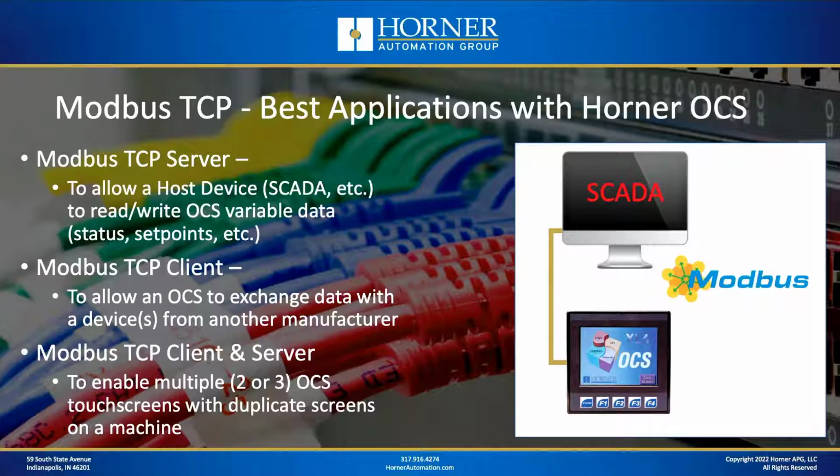In the scenario where the OCS is the server, it's a great way to provide access to all the OCS variables, or at least as many as you want to share, with a SCADA package or some other host software package. It's probably not going to cost you anything extra on the host software side because it probably has a Modbus driver built in, and all the OCS memory types are directly mapped over to Modbus data types as well.